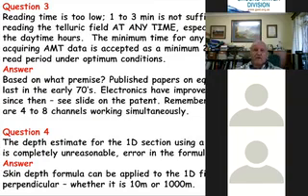Nevertheless, there's another thing: how long does a reading take? If you're doing a resistivity sounding, you're setting up your current electrodes and your potential electrodes and putting them further and further apart. The sounding will take you anything from half an hour to 1.5 hours if you're going down to 50 meters, to 150 meters, and you'll have about 14 readings.